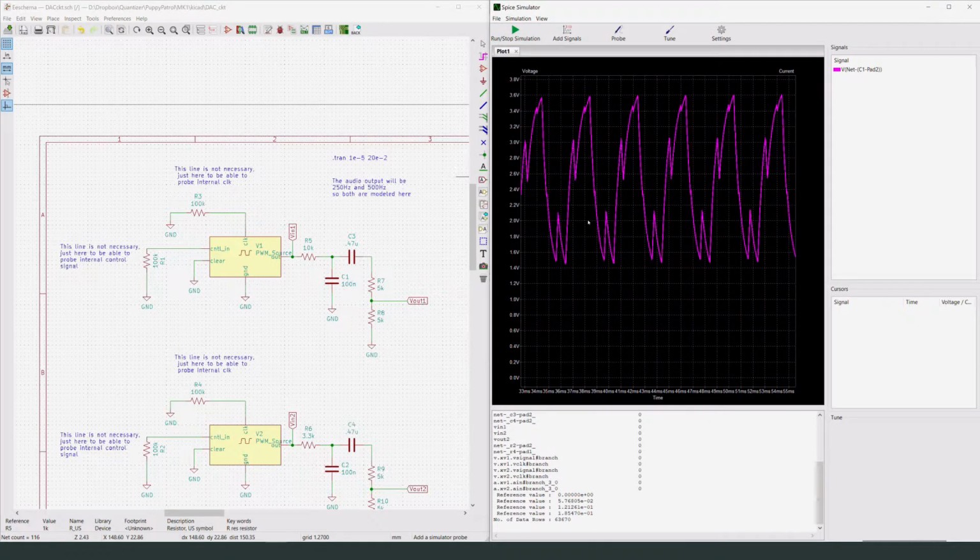And you'll see that this is a much smoother signal, right? You could keep going up, but you start to run into a problem where you'll notice that this signal was smaller than the earlier one, because this low pass filter is going to filter out or attenuate or lessen the peak to peak voltage value of higher frequency signals. So you have a trade-off you have to deal with.